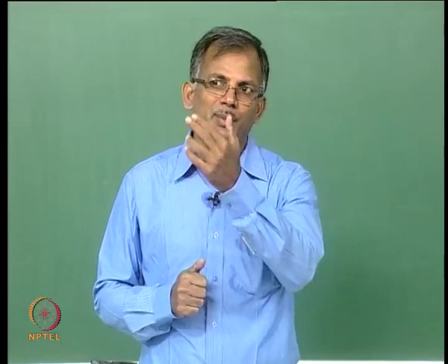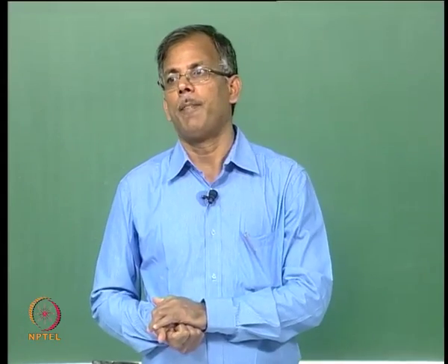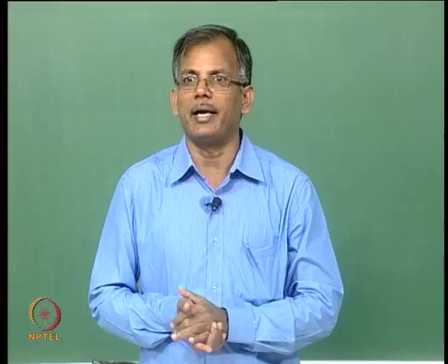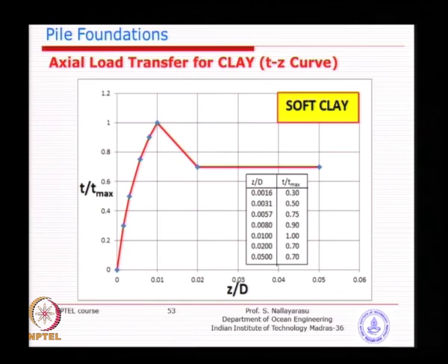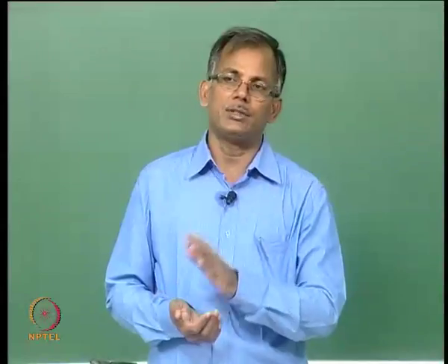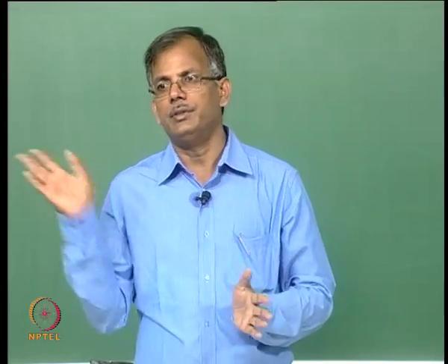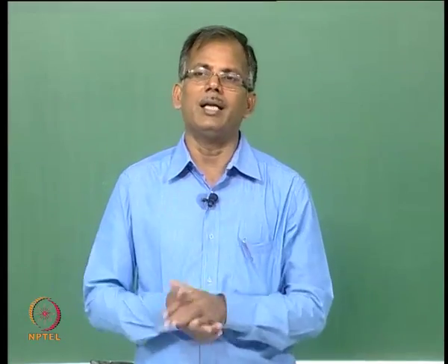Even though we call stiff clay better for foundations, for pile foundations it is not very good, because you will not be able to get the skin friction back. That is one of the issues determined by several researchers through field testing, and they demarcated that we have to differentiate between the advantage of soft clay versus the disadvantage of hard or stiff clay. For soft clay, the demarcation is 96 kilopascal. So, if the undrained shear strength is less than 96 kilopascal, it is called soft clay, and beyond that it is not. Approximately, you can remember 100 kPa.